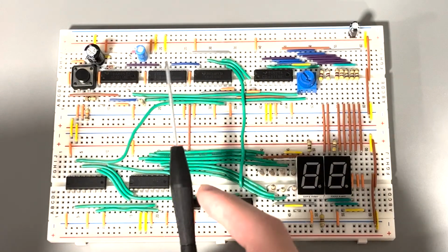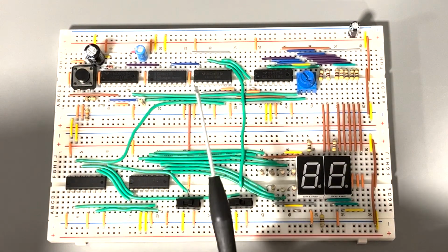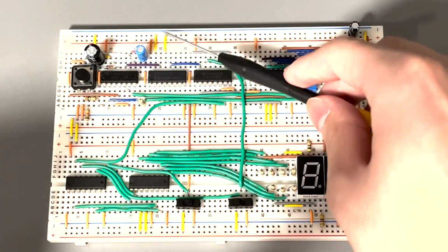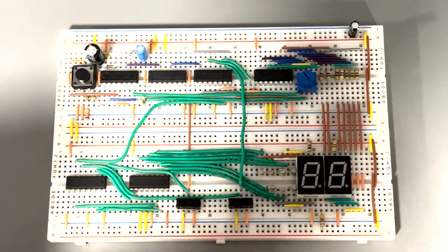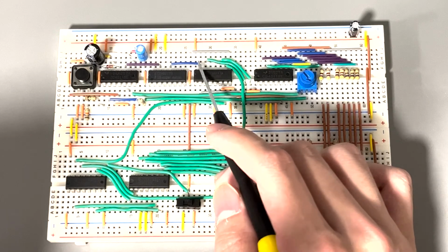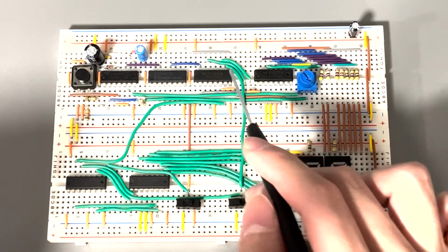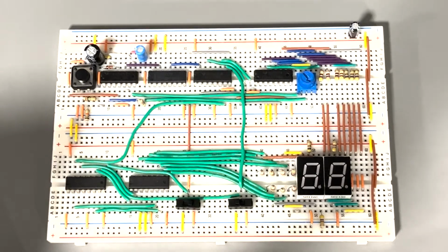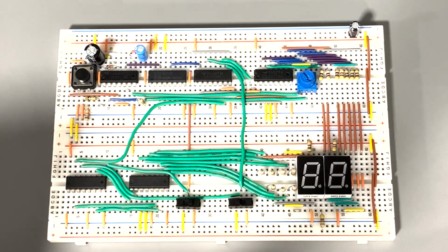Moreover, pin 15 and 13, the reset and the enable pin of the 4017, need to be conditioned, which in this case means that they have to be grounded. The divide by 10 output is inputted into pin 15 of the 4510. The 4510 counts each of the rising edges of the clock signal and turns it into a binary number on its output. It counts from 0 to 9, and then it resets back to 0.